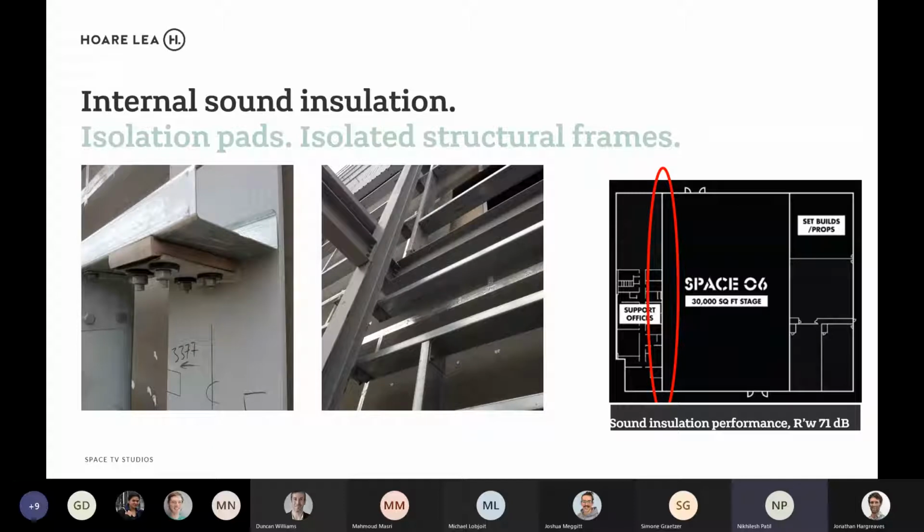Likewise, even after you have done your separation of frames, obviously, because it's the real world, there will need to be some connections that cannot be avoided just because the structure demands it. And this is where the design negotiation comes into place. Let's first minimize the connections. And if there are any connections, what can we do about it? Let's have a soft joint wherever possible.